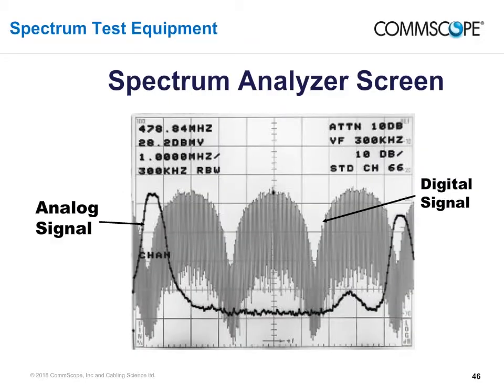Although simple meters can be used for some of these measurements, most technicians will also need to become familiar with the operation of a spectrum analyzer, to view signals across a range of frequencies. The main components of a spectrum analyzer are an RF receiver and a visual output that displays a signal's amplitude and frequency components. The RF receiver continually tunes across a selected band of frequencies, so the display is the spectrum within that band. The number of controls and display options vary with the models and manufacturers of spectrum analyzers.